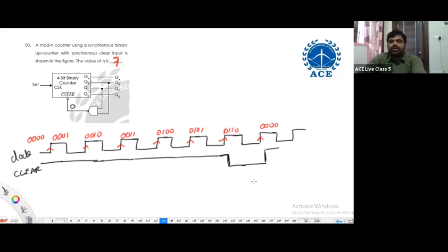Yeah, in this, even though you are not defining which one is MSB, which one is LSB, it doesn't matter. In this, it is not required to specify. Whichever the order you are considering, it will be the same sequence because the middle ones QB, QC are both expected to be 1-1. You can use any order in this question. But if you are using any specific sequence on clearing, then obviously they have to specify. Chakrabarti, good question. In this, the order doesn't matter for us.